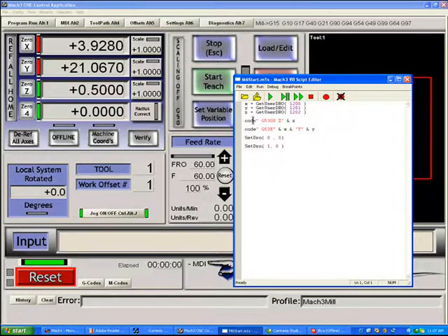Now the problem here is that we commanded moves, and then we said set the DROs to 0. These DROs were set to 0 during the move. There is a safety command that we need to put between some codes. And whenever you're having strange effects, I recommend you put one. We put the word while, the macro command is moving, and then command wend. This is a while wend loop. A while wend loop based on is moving tells the system to stay here as long as previous commands are executing. When they're finished executing, then execute on into the program.